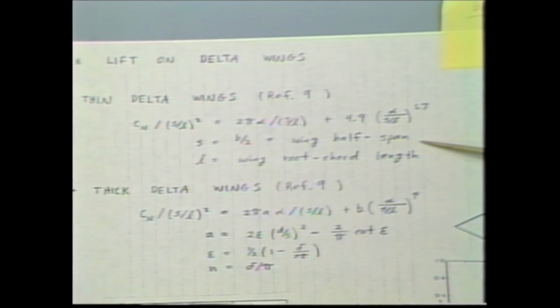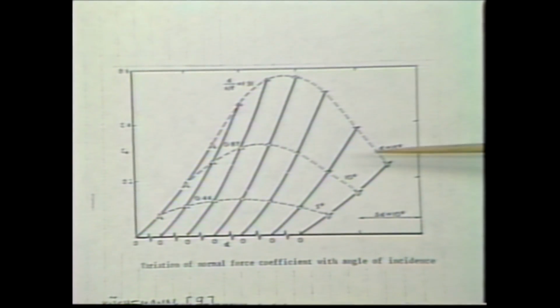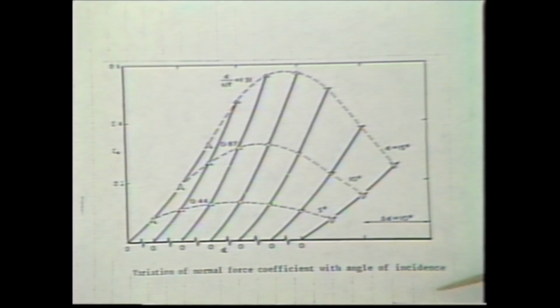Similar data and correlations are shown here for delta wings. It also points out a thickness effect having to do with the leading edge. Basically, the leading edge angle is the correlating parameter there. So for a delta shape, and our actual wing might be more delta shaped. And then lastly, just briefly, anhedral and dihedral do impact that nonlinear lift. And you can pick that out pretty well from that data.